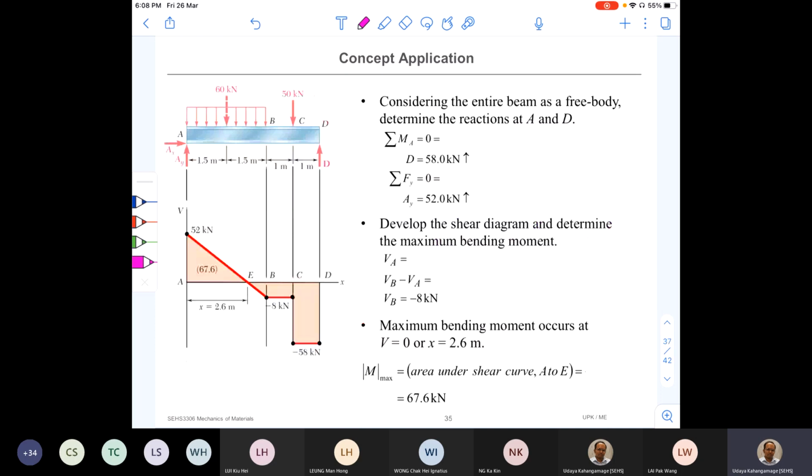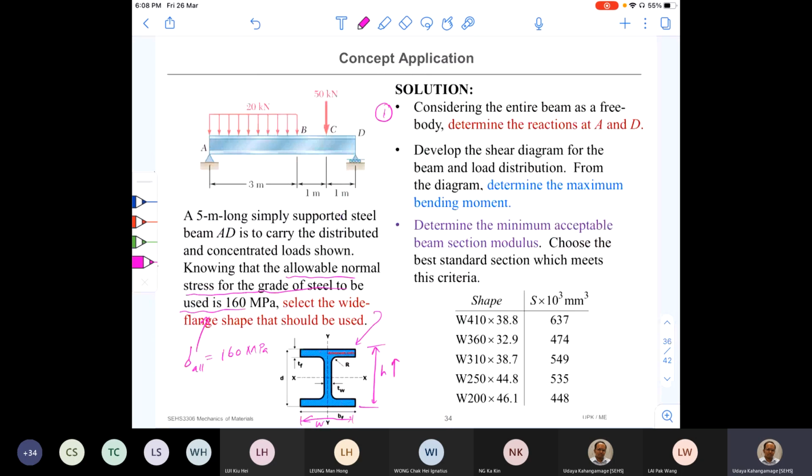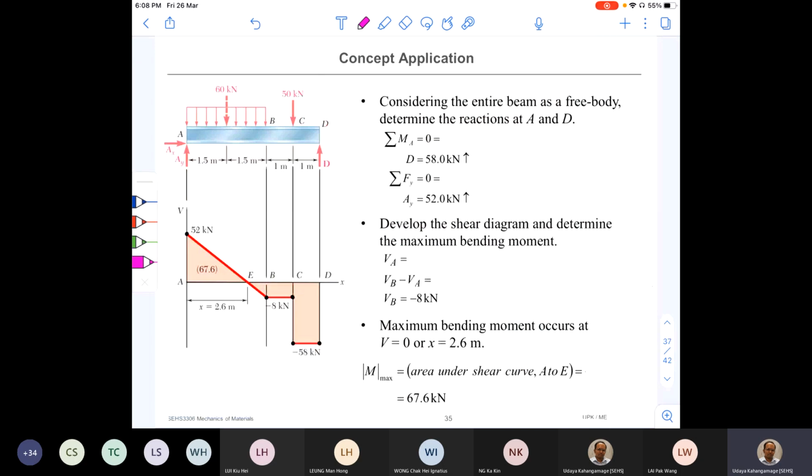I have drawn the free body diagram, and I have also constructed my shear force diagram. I'll explain how I constructed that. Point A here is a pin joint. Point D is free to move, it is the roller support. Therefore, potentially there can be an axial force and a vertical force at point A. But by observation, I can say that the axial force is 0.